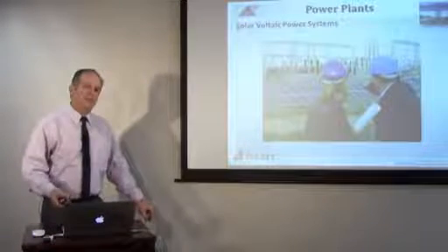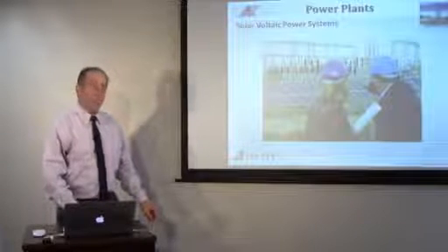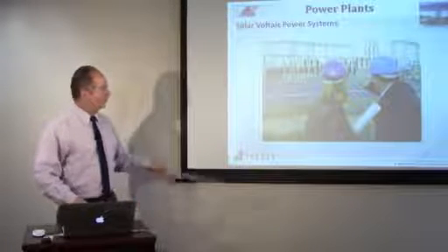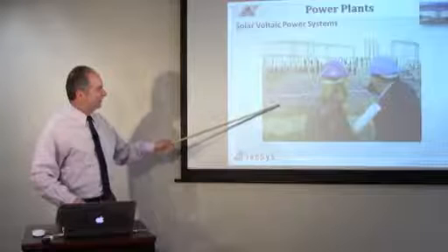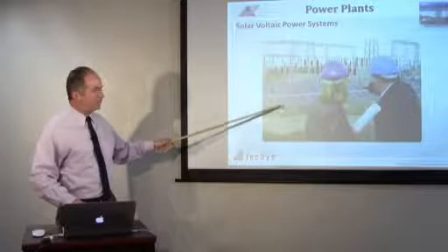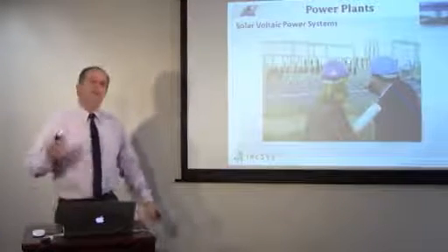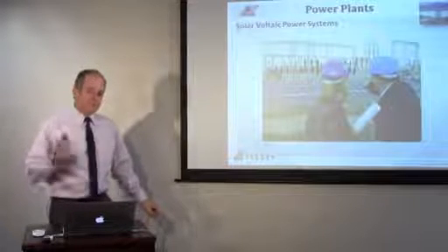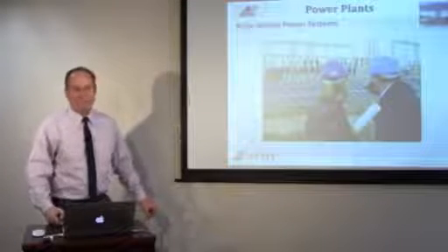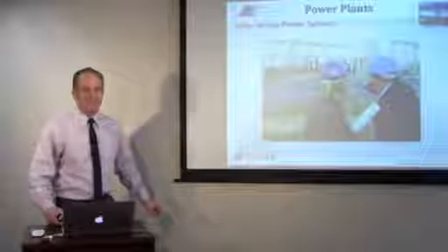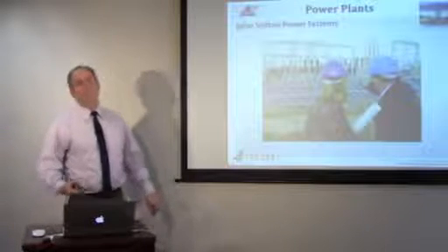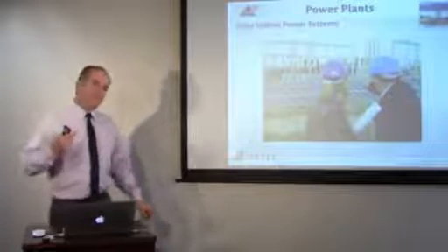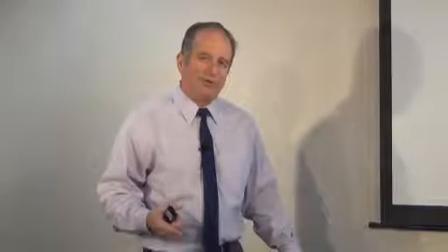Now the sun energy into electrical energy. Each one of these little dinky cells, there's one little cell, but that's made up of multiple cells in itself. A little cell only produces 1.2 volts and maybe 20 milliamps. It's not huge. But if you take the 1.2 volts and put 100 of them, now you have 120 volts, if you put them in series, still at 20 milliamps.